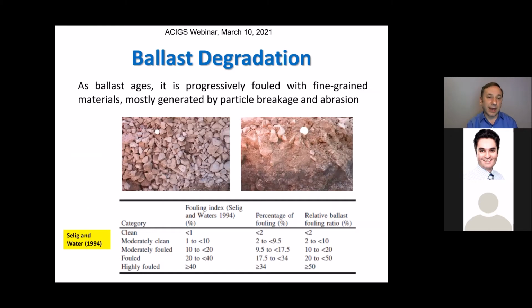The other fascinating thing about ballast is that it is typically uniform sized, as we all know, and this uniform size with a large void structure takes the load and gets the heavy pounding, the channelized load under the rails. With that, the aggregate materials start to abrade and break down, and that's how fine materials are created. Fine materials slowly cause the ballast to consolidate and densify, but at the same time, with fines increasing in content, what we call fouling of ballast takes place.